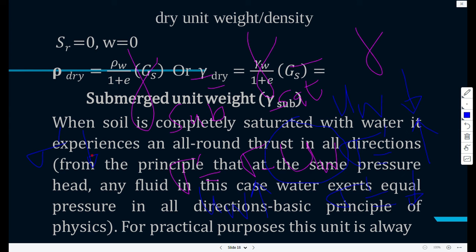So because of the increase of the pore water pressure, the sand particles lose their weight. They become kind of weightless, so they can be thrown away because the pore water pressure has already increased beyond the expected value. So then the soil particles are no longer stable. That's why they are carried all over.